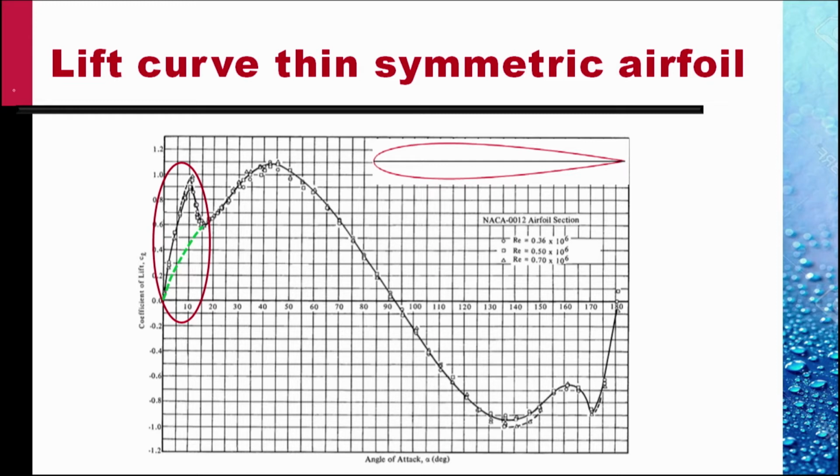In fact, Wright brothers are credited with this discovery when they suspected that the data they were working with was oversimplified and conducted their own experiments, where they found that the lift produced by aerofoils rose sharper than alpha for a flat plate. The rest of the curve, except for this region, behaves as if it is a flat plate.